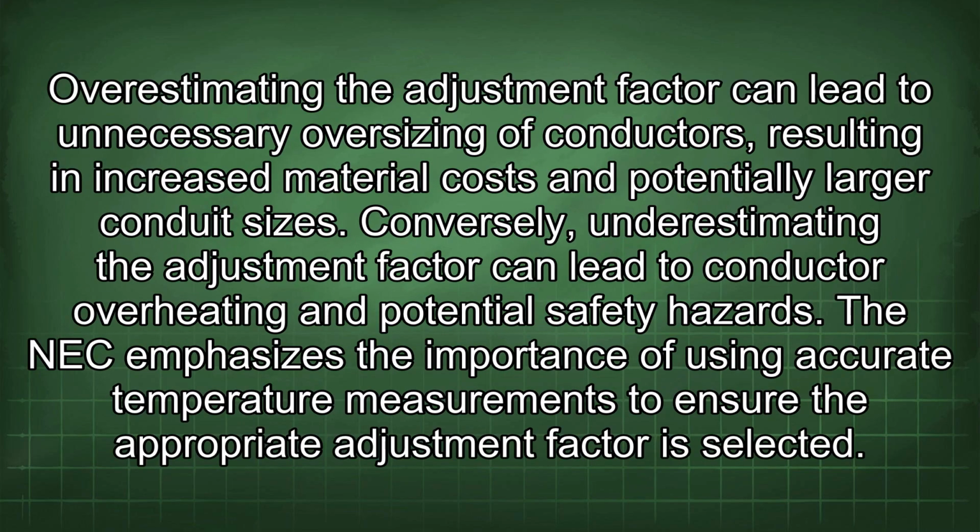Overestimating the adjustment factor can lead to unnecessary oversizing of conductors, resulting in increased material costs and potentially larger conduit sizes. Conversely, underestimating the adjustment factor can lead to conductor overheating and potential safety hazards. The NEC emphasizes the importance of using accurate temperature measurements to ensure the appropriate adjustment factor is selected.